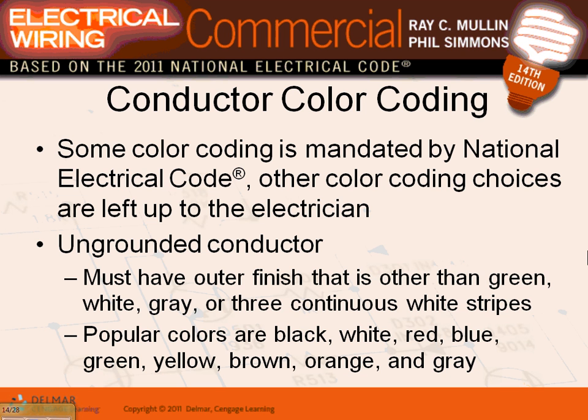Any questions, guys, about the receptacles or the switches? The only thing is where to put GFCI receptacles. Do you need an isolated ground receptacle? Yep, only if there's interference with electronic equipment.